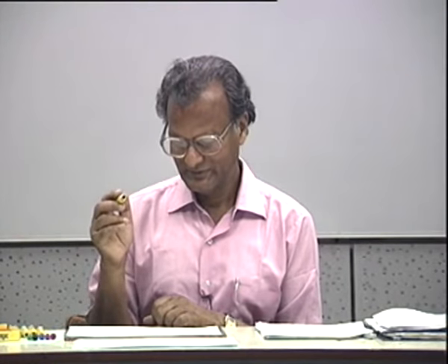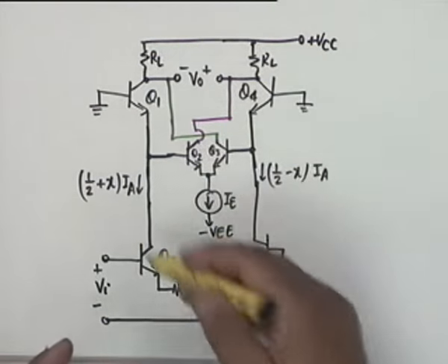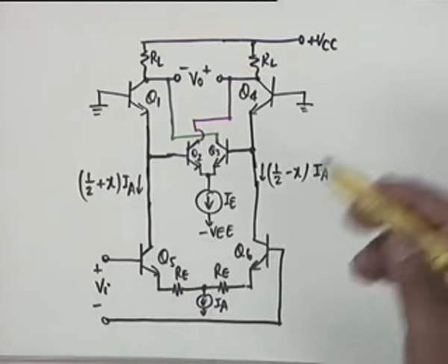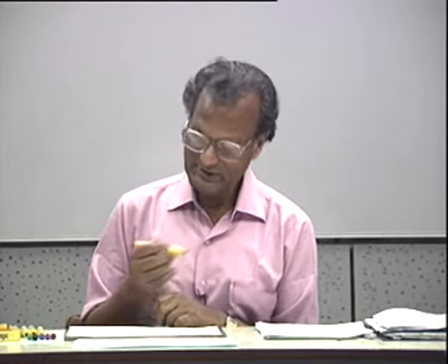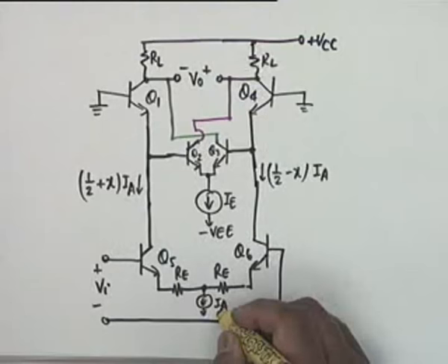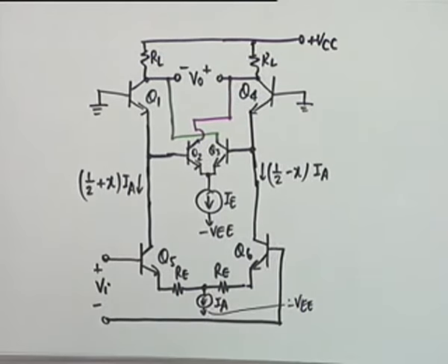Okay. Why do we need minus V below I? Why do I need this? Well, you know that in an op-amp, in a differential amplifier, there are two supplies that are needed. Even IA is going to minus V. That is also going to minus V, yes. This is also going to a negative supply. As I said, this is not essential, but I have also explained the reason why two supplies are used.